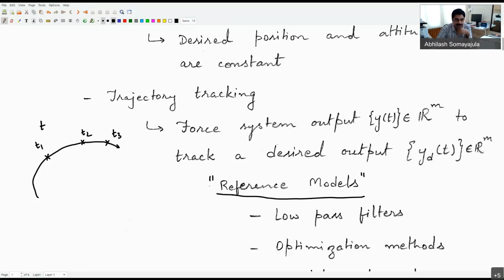What I mean by reference model, in the strictest sense, is this: let's say I have a craft that I want to track, let's say the KCS. I build a good enough detailed model of my KCS and simply use it to simulate a trajectory, and that becomes my so-called desired path. When I do the simulation, I know for sure that it has taken into account the dynamics of the craft in finding the path. So the path which I have generated through the simulation is more likely to be closer to a path that can actually be followed. Is that making sense?